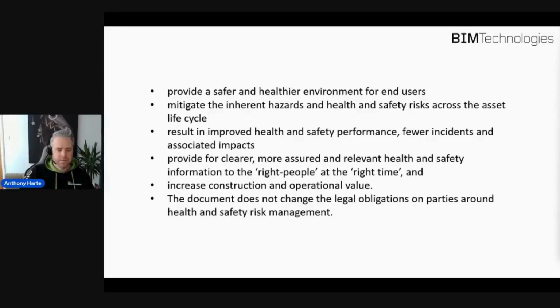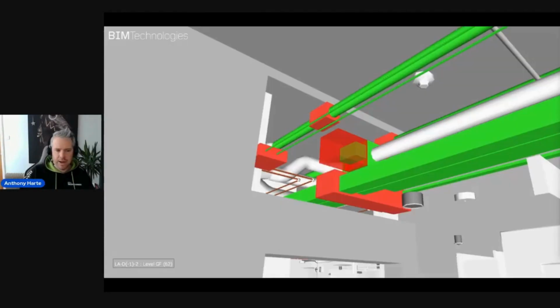Other ways we're seeing this play out as well is, we're again thinking of fire and thinking of fireproofing in buildings. We have here an image of various services going through a builder's work hole within a building, and the team responsible for this have put in the fireproofing. However, it's a very bad example, and I just wanted to point this out. So the opening in the firewall is a single large opening with multiple surfaces, but the red boxes you see here are the requirements for fireproofing.